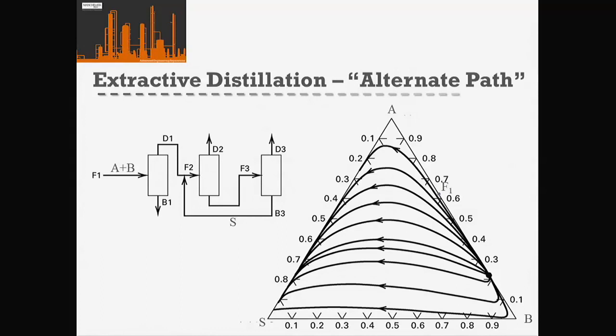So what that means is when you're actually undertaking the distillation, you can't think of that component as always being a liquid. It will vaporize itself. Therefore, you actually get a split of that component potentially between the top and the bottom of the column. Yeah, and that component vaporizes on the different stages, actually taking part in the equilibrium.